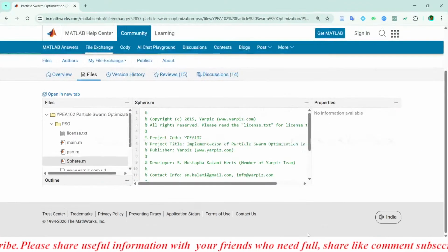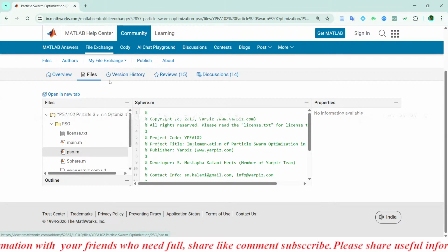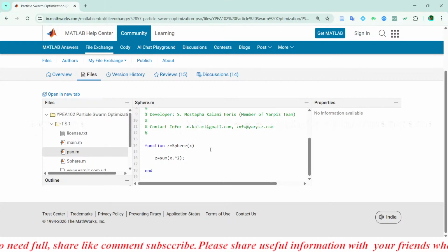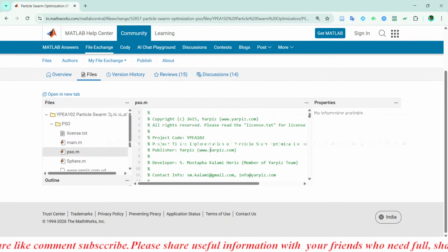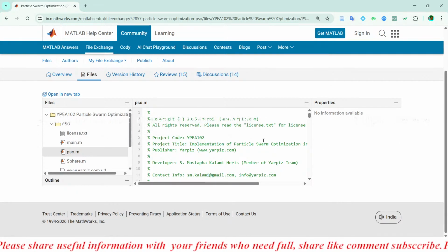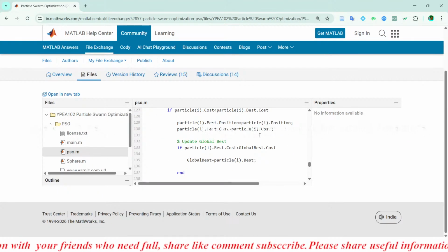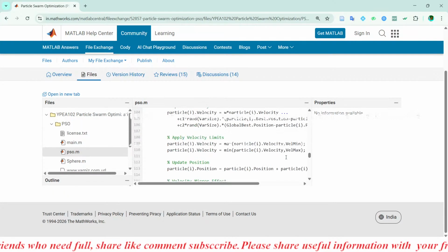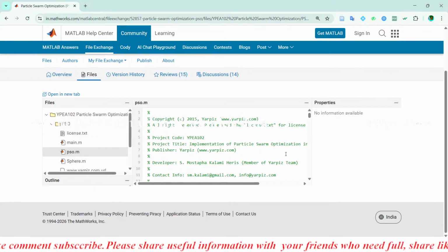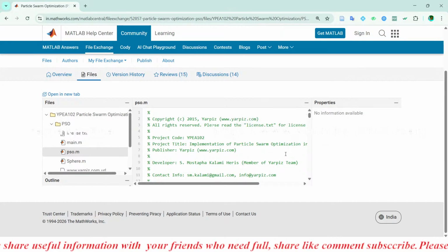Okay, so here you can download any algorithm files in the MATLAB file exchange. But you need to write your own cost function depending on which objective you want to do: ITAE, IAE, error based, or multi-objective. Either frequency based or transient, time response, that you need to choose depending upon the desired response of your output. So these are the things you need to be careful about while doing optimization.